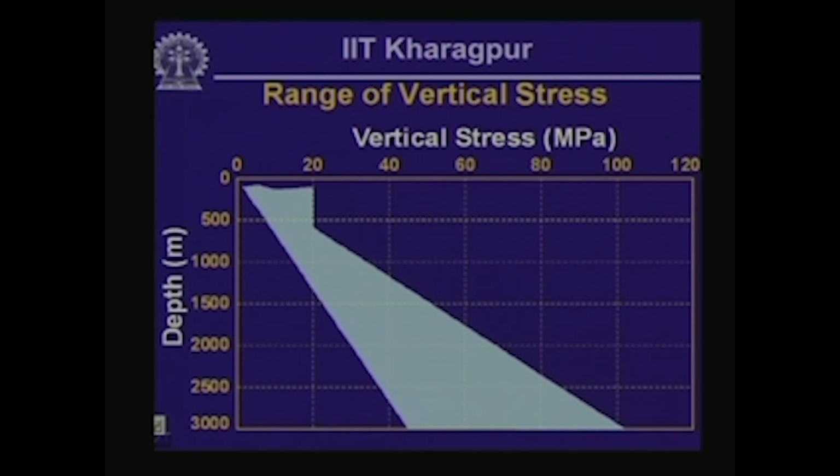So that will give you an approximate estimate of the vertical stress within a mass of rock at some depth below the surface. This estimate is not going to work that well very near the surface, but if you go down to relatively greater depths like 500 to 1000 meters, then this method is going to work quite reasonably.